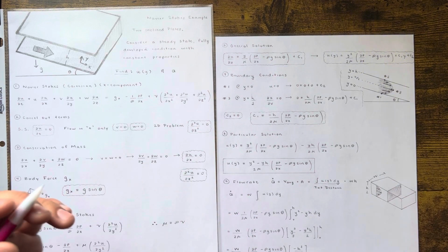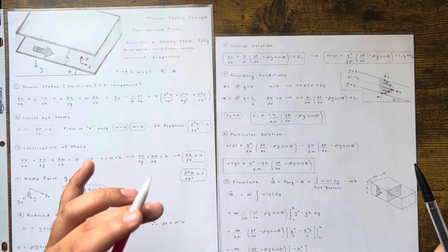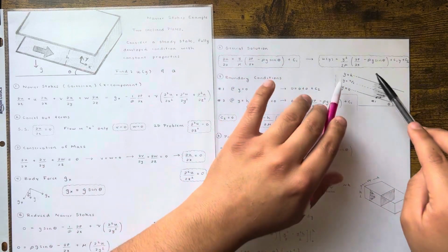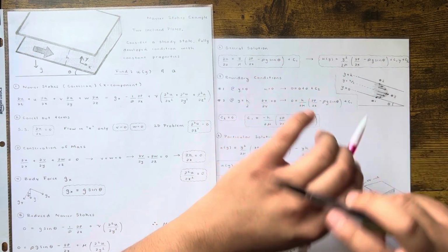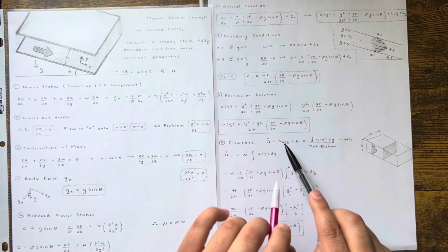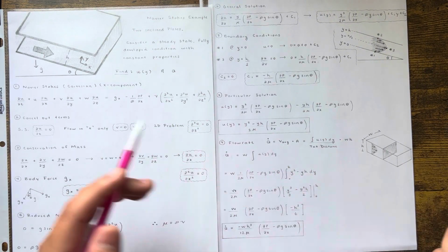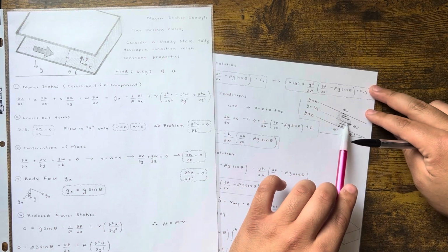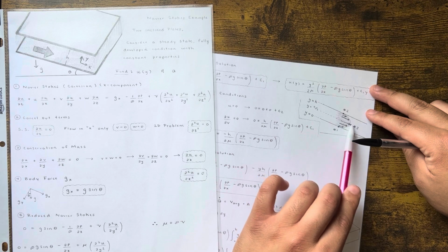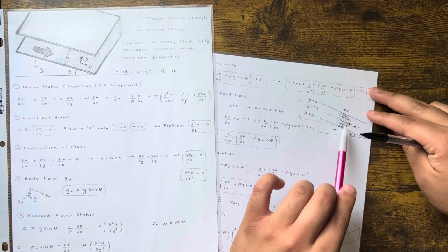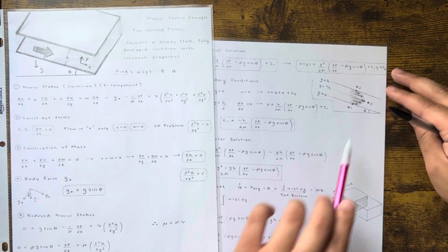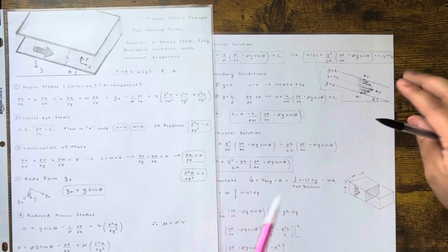That's exactly what this tells you, right? That's the whole point of Navier-Stokes. It tells you the velocity profile. So this isn't average velocity, my bad, I got sidetracked. This is a velocity profile, not average velocity. So we need the average velocity. So how do you get the average? You just get the integral, right? This is a curve. We want the area under the curve. Because the velocity is high here, it's 0 here, it's 0 here, it's symmetrical, but where is the average? So it's easy. All you do is take the integral, and then you divide it by your total height.